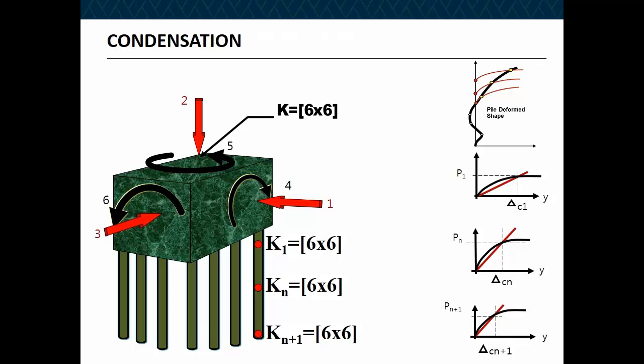You model the foundation, you push the foundation or the pile to come up with a deformed shape. And as a function of the deformed shape, you put a 6x6 matrix at every node, because remember, this is an element which has six degrees of freedom at each node. The foundation springs are linearized and incorporated into the 6x6 matrix at the element.